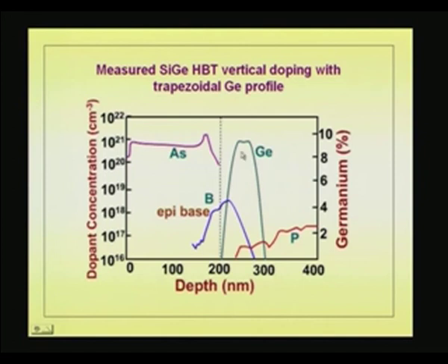They have not shown that gradation that much in this case, but you can see from here to here the gradation is there. Germanium gradation means the band gap is varying from larger to smaller value, so there is a built-in field coming up. Okay. And the percentage of germanium goes right up to about 10%, 0.1. So, the band gap is narrower compared to that.